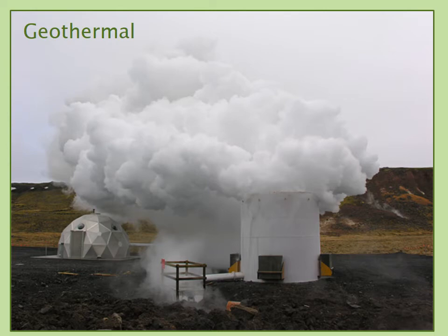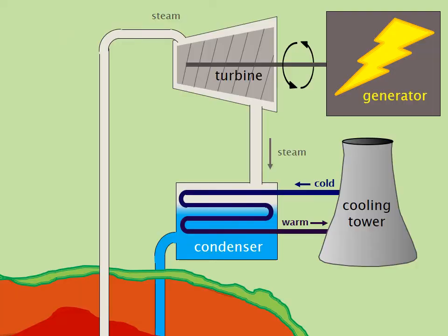Next is the production of electricity through geothermal energy. When geothermal energy is used to produce electricity, they take water and they push it below ground. It is so hot where they conduct geothermal energy for electricity that the ground is able to heat that water into steam. And the steam then pushes the blades of the turbine. When the turbine spins, it spins the generator producing electricity. They then recondense that steam into water, and then that water is pushed down below ground again.